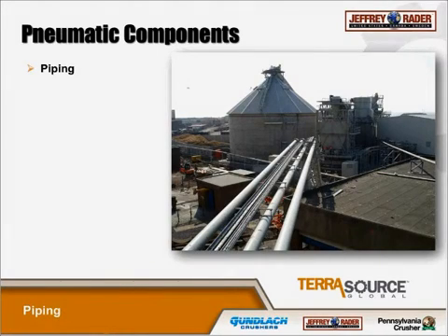Here's some piping. Got mild steel all the way to abrasion resistant varieties. It's better to run horizontal and vertical than at a slope, as is shown in this picture. When you're running at a slope, gravity is acting on the material, and it's going to increase the friction. Think of it as the material bouncing in a stepping pattern up or down the slope. It's just not good for the system. When you're running with just horizontal and vertical pipes, it creates less friction, fewer pressure losses, lower horsepower, saves you money.